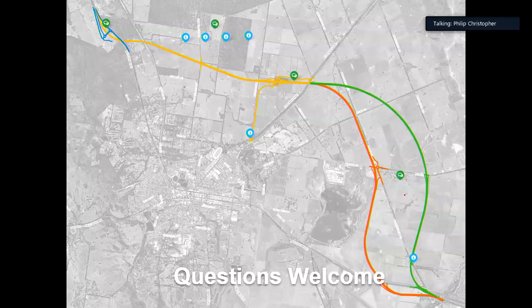Yes. When you thought about the conceptual design, how detailed do we need to go? Do we need to design the reinforcement for the foundation and also for the bridge, or we don't need to? Great question. The level of detail in the design is not to the degree of reinforcement. It's dimensional detail. So, how high is your bridge, how long, how wide, what Super Ts you're using, but definitely no reinforcement detailing or, say, parapet design or any of that. We're really one step back from that. It's really high-level conceptual design.